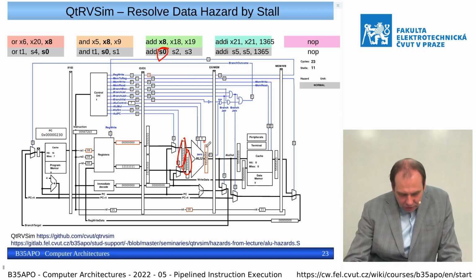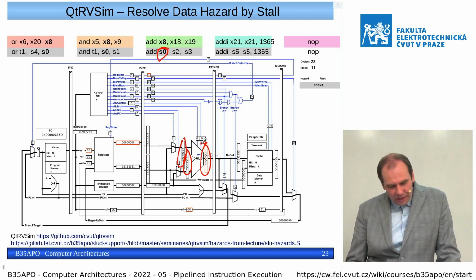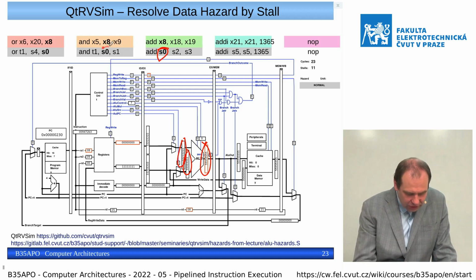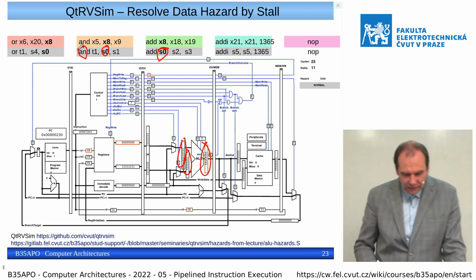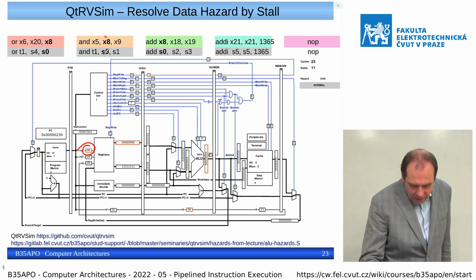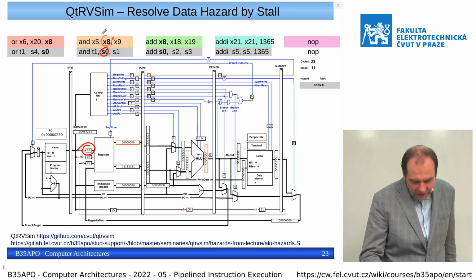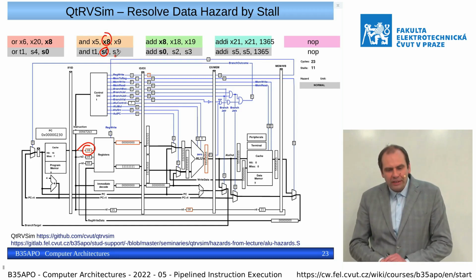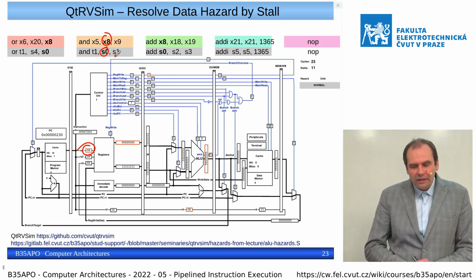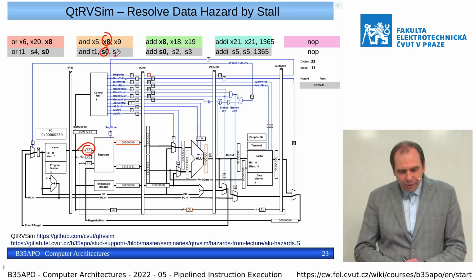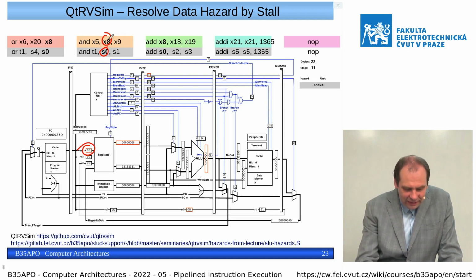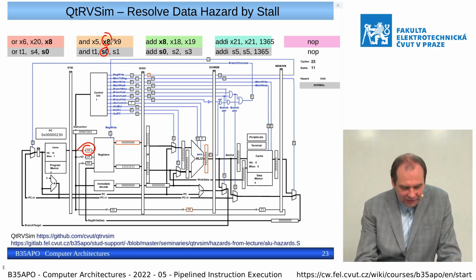On the arithmetic logic unit, we have the output 5, 5, 5, 5, which is the correct result. But the follow-up instruction from our previous sequence already requires reading the register S0, which is the physical register 8. Those S names are mnemonic names for the registers. S registers are for local function variables, T are temporaries, A are arguments, and so on. So in this case, the S0 is exactly the physical register X8.